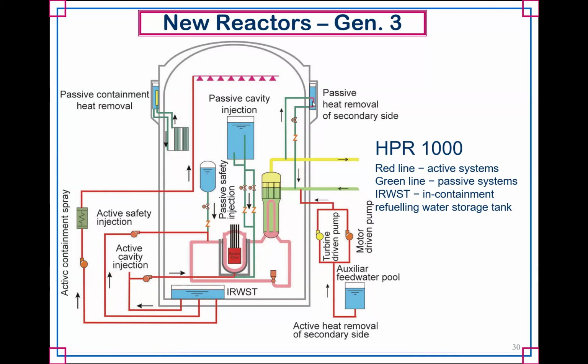So you have water that is located outside the reactor, and it's basically a heat exchanger. As the water goes up, it's heated, it runs into this cooler surface that is exposed to the environment through a heat exchanger. It cools down, and then it completes the process over. You can see there's also some feed water pools. Again, this is just put in place if you wanted to speed up the process, because you do have power on site. You can do a lot of this stuff much, much faster.